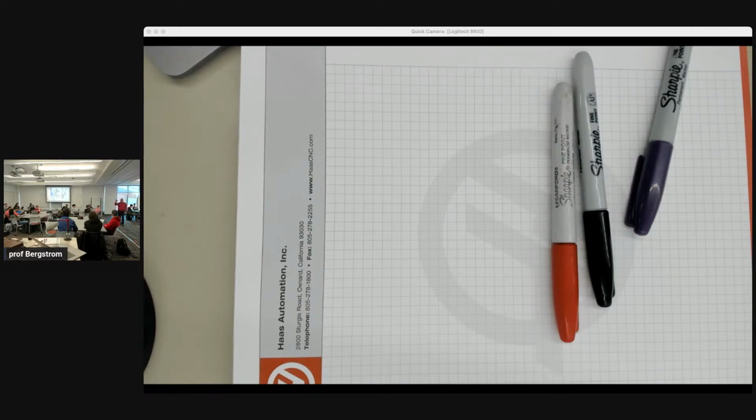On the controller, you can get to the distance to go menu. Depending on which machine you are, it's a slightly different process to get there. But you get to that distance to go menu, and it'll say Z negative 0.981. So if I look in, and it's about an inch away from the part, but I know it's going to 0.1 above, that would be like 0.99, right? So 0.981, and I'm estimating that inch. Yeah, I'll buy that. Probably set it up correctly.